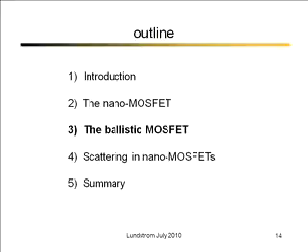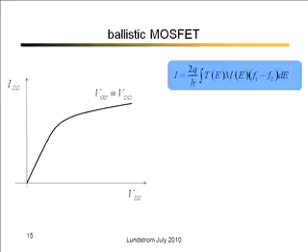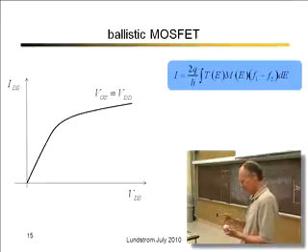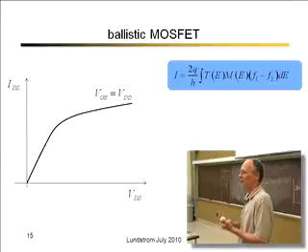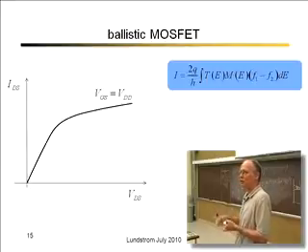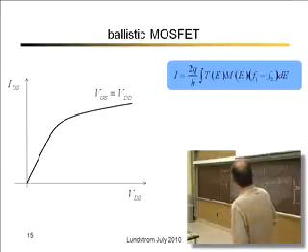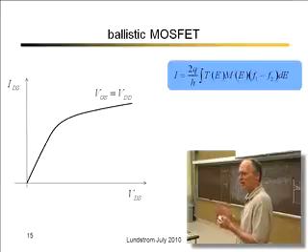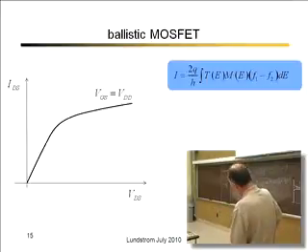So first of all, we'll take the case where there's no scattering. The IV characteristics of any transistor are going to look similar. It doesn't matter whether we treat them with a classical model, a quantum model, or a drift diffusion model. They're mainly controlled by modulating these energy barriers, so they all have the same shape. The transport model affects the magnitude of the current somewhat, but doesn't change its fundamental shape. They'll all look something like this.